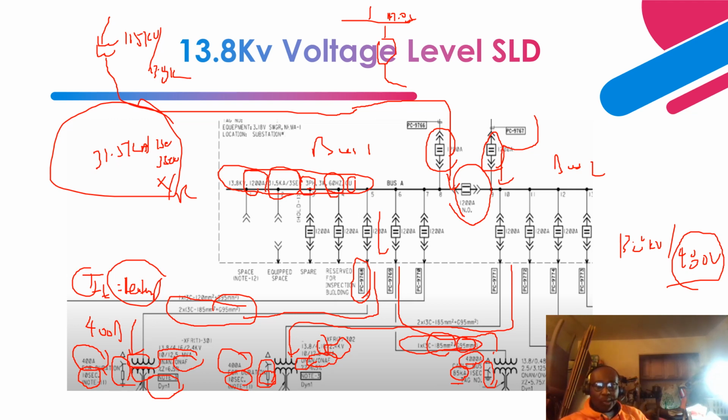So it goes to this step down transformer with a voltage step down 13.8 kV to 0.48 kV. Then this is the rating of the transformer, 2.5 ONAN rating. That is natural convection, natural flow of air without any fans, and ONAF of 3.125 MVA, right?